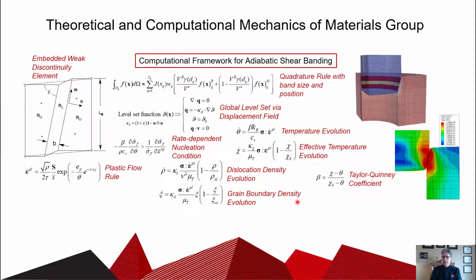So I also care about what's called adiabatic shear banding, another important deformation mode. So this is very common in typical machining procedures. And this is the type of loading event where the temperatures of the material can be raised hundreds of degrees Celsius. And deformation is in very small regions of the material. And this is another form of damage, but without adiabatic shear banding, we wouldn't be able to machine materials for common day use. So another very interesting and very important area for us to study.